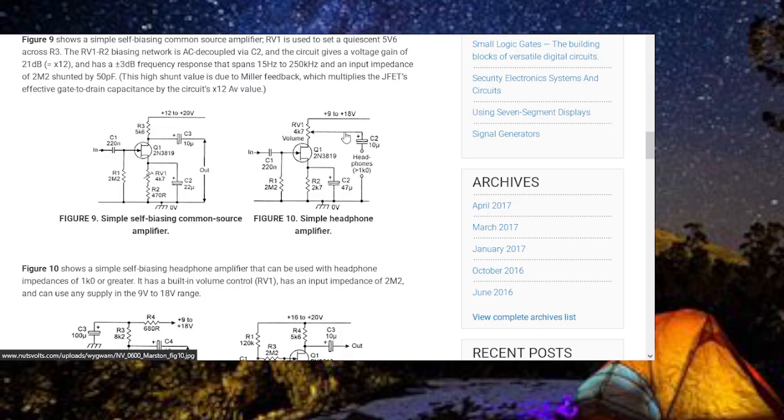I don't know, this FET has mega amounts of gain. Say you've got a 1 millivolt signal and you want to crank it up to 1 volt or something like that. It's got such a high gain that you can put some components in there. You can build in a filter, and some other stuff, maybe even an ALC circuit, which controls the level coming in, to keep the noise way down.